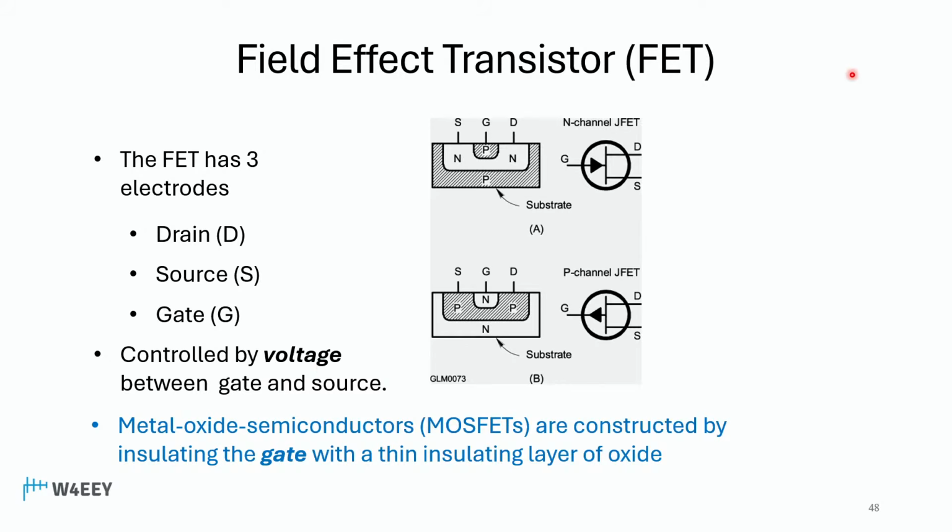Then we've got field effect transistors. And the same Gary's trick of the arrow pointing toward the N material works for us here. That'll become important later in life. So this is a field effect transistor. We've got a junction field effect transistor, or JFET. It's got some P material as a substrate, and it's got an N channel, and then P for the gate. So these are the internal components.